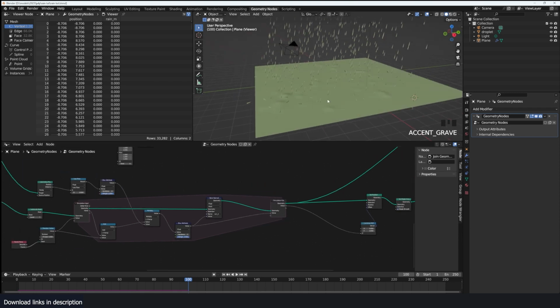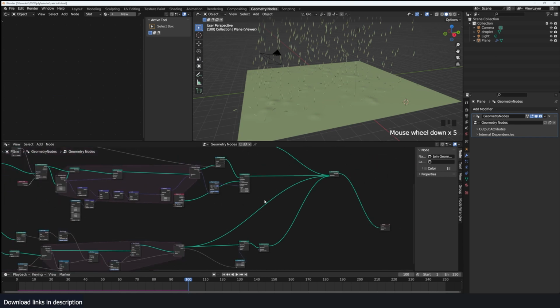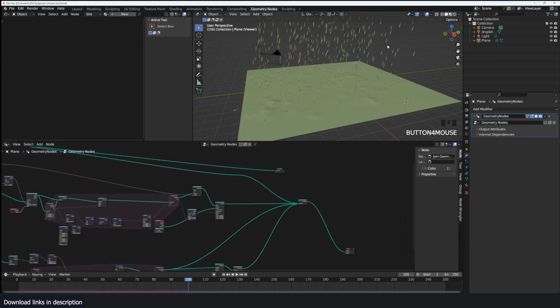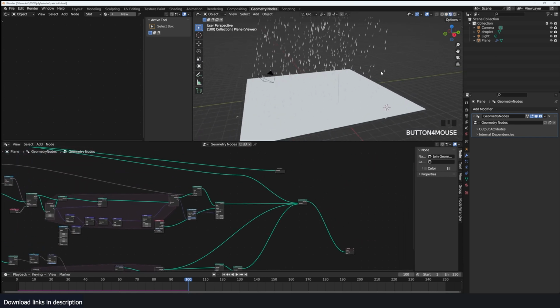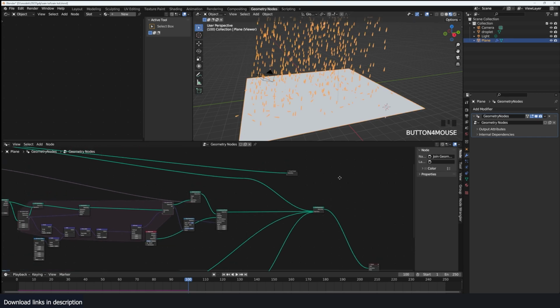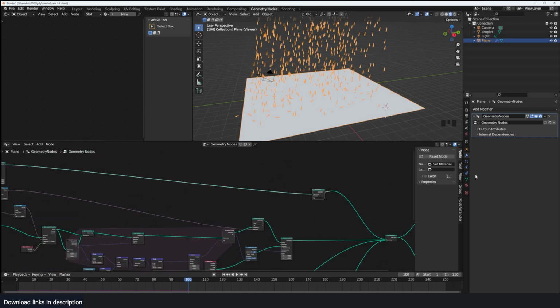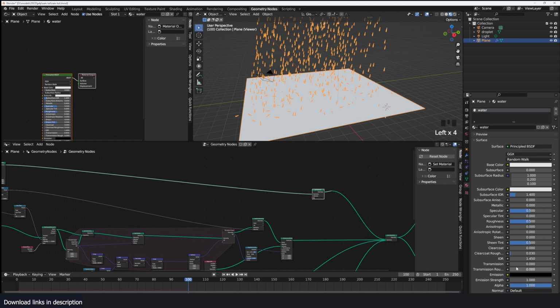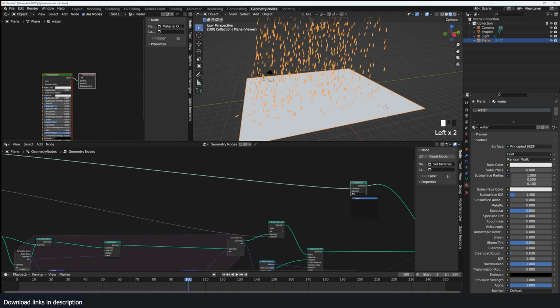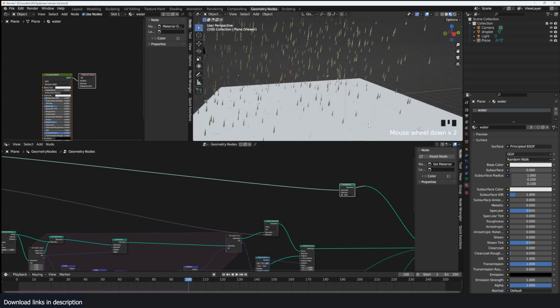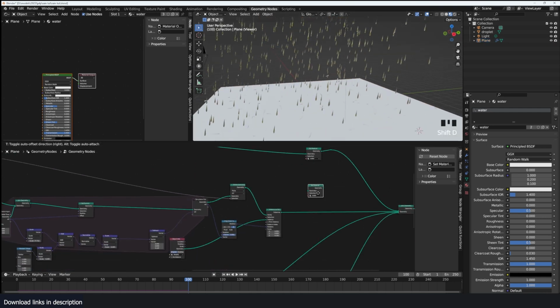So now we can go into the materials. I can start with the water droplet. So I can use a set material that creates a water droplet here. So it's going to be full transmission, no roughness. Let's apply that to the water like that. We also want it to be on the droplets.